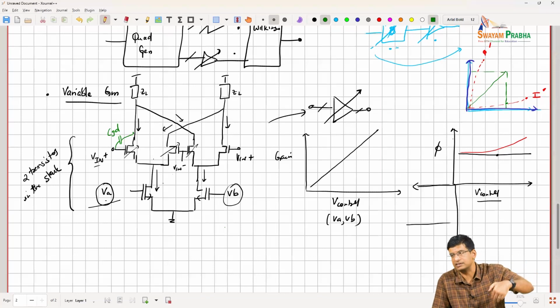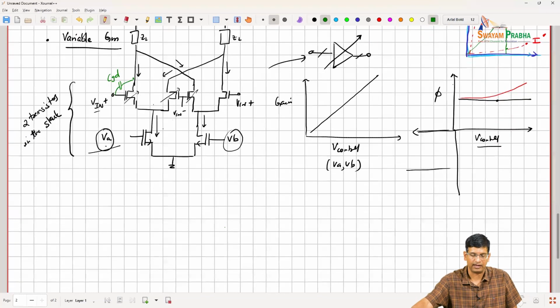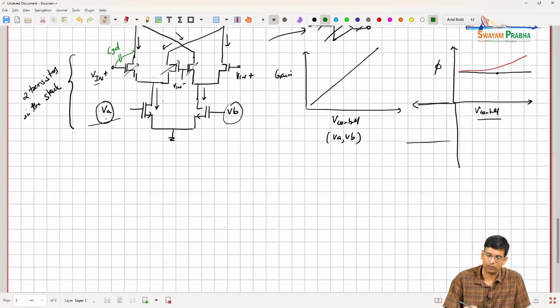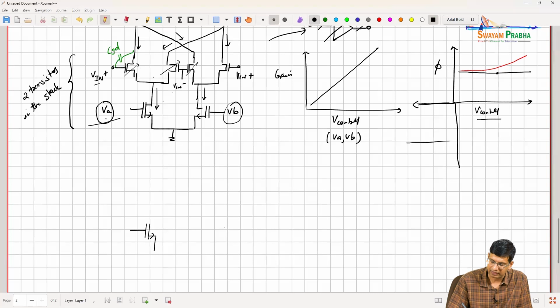So you start seeing a variable gain, so a variable phase. So the traditional approach is always to cross couple, or to neutralize, sorry. So once you are ready to do that, you can even get away with a single stage design where your amplifier looks effectively like this.